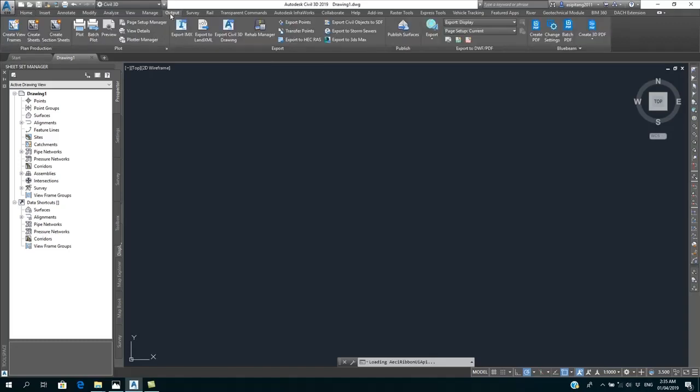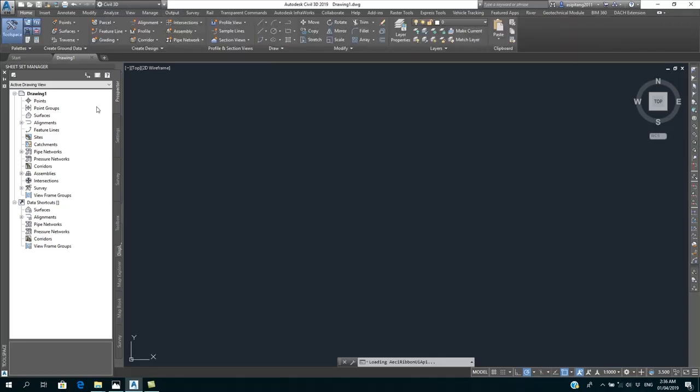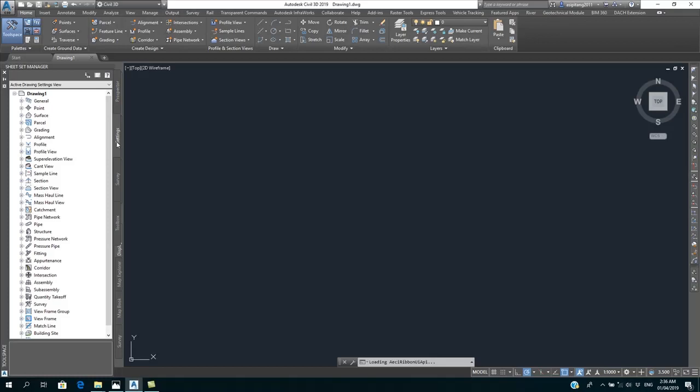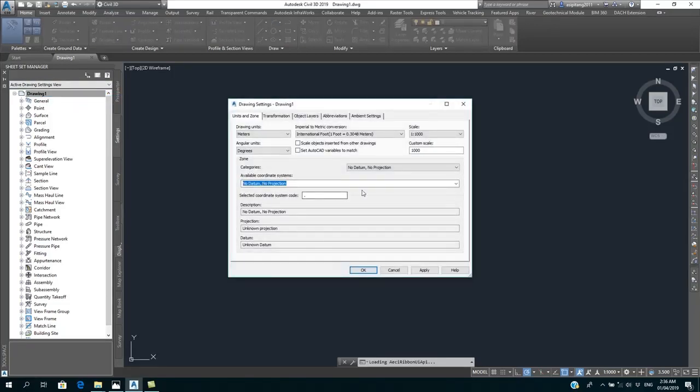So in this case, we can decide that this kind of project I'm working on needs to be opened in Infraworks. So I need to do a projection by editing the drawing settings to give me a data projection with the coordinate system I'm using. In this situation, it means that you must reference your data with a specific coordinate system position.